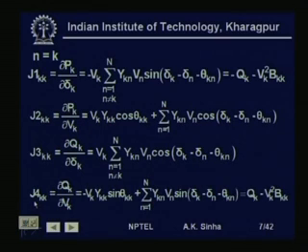And J4kk, that is the diagonal elements of J4, ∂Qk/∂Vk is equal to minus Vk Ykk sin θkk plus the summation from n = 1 to N of Ykn Vn sin(δk − δn − θkn). This is equal to Qk minus Vk² Bkk.